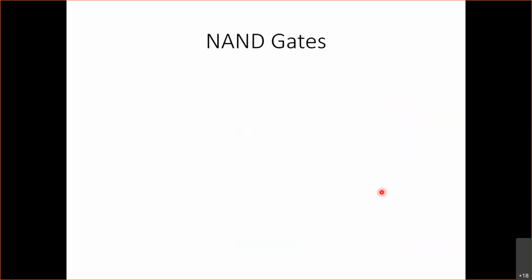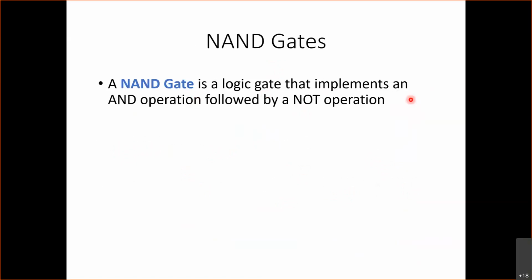Okay, I'll take a look at NAND gates first. A NAND gate is a logic gate that implements an AND operation followed by a NOT operation. So it looks something like this. We have an AND gate and we put a bubble at the output. And the operation being performed here is C equals NOT (A and B).